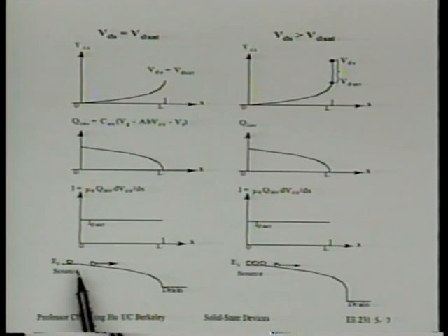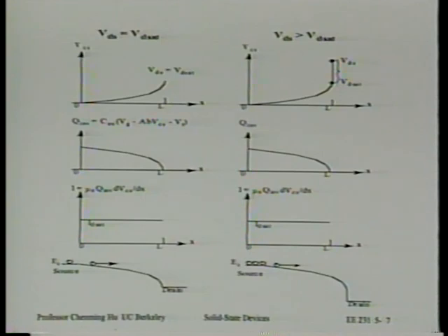Here I'm drawing the energy band diagram for this curve. Of course, as you know, the energy band diagram is just the potential profile flipped around, the mirror image of the potential profile. We draw the EC at the source, EC at the drain. We show almost no barrier between the source and channel. This is because we're assuming strong inversion, right? The electron density is very high. The VG has bent the EC almost as low as the conduction band. In other words, the electron concentration in the channel at the source is almost equal to the source doping concentration. And the electrons, therefore, flow down this potential hill happily until they reach the drain.